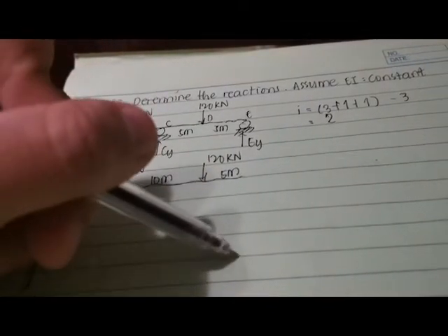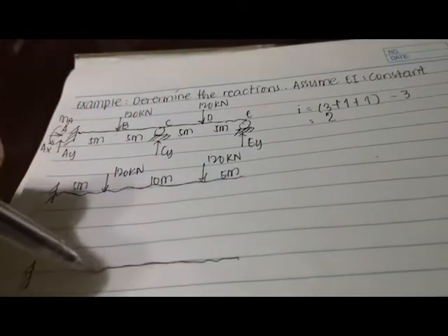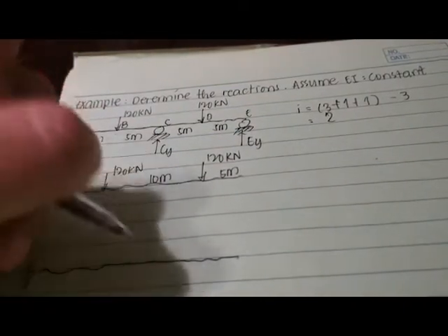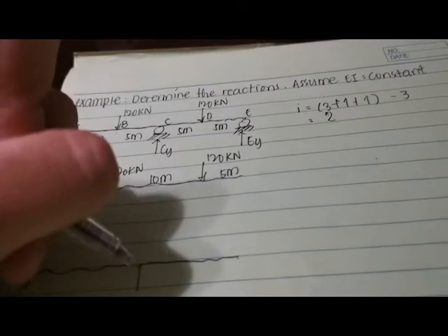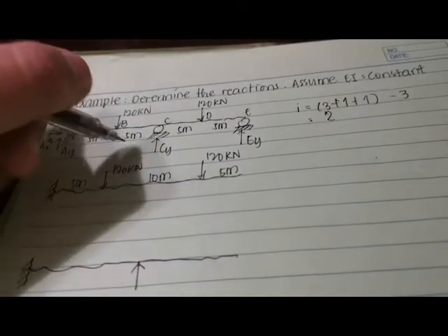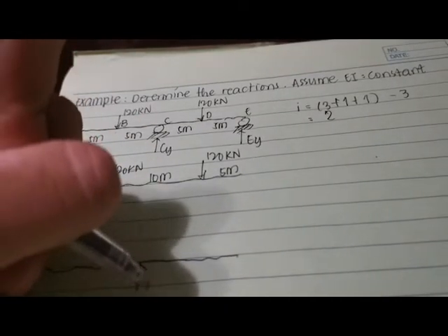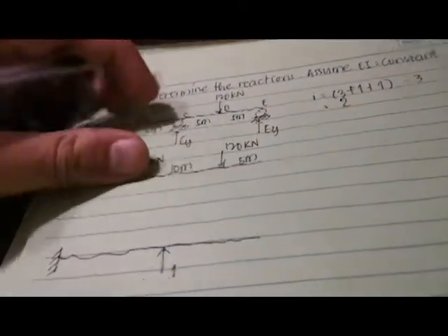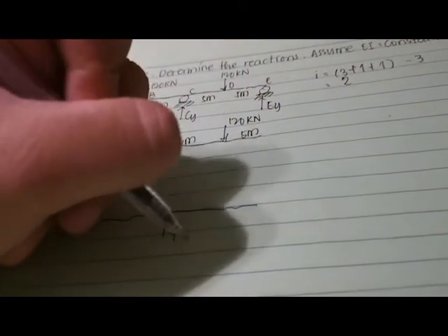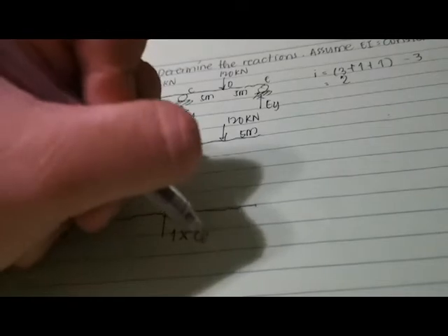Next, we're going to remove the original loads, we're going to remove the loadings, and then we're going to return the reactions by applying a unit load. In this case, we're going to apply a unit load at C. So this will become 1 multiplied by CY.